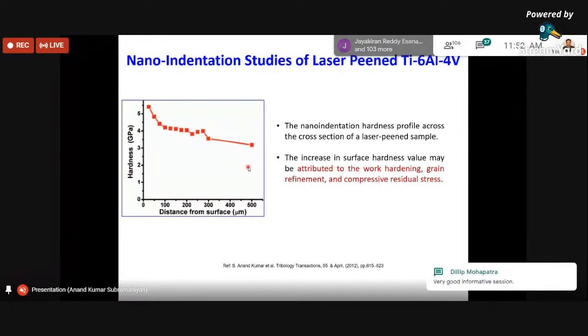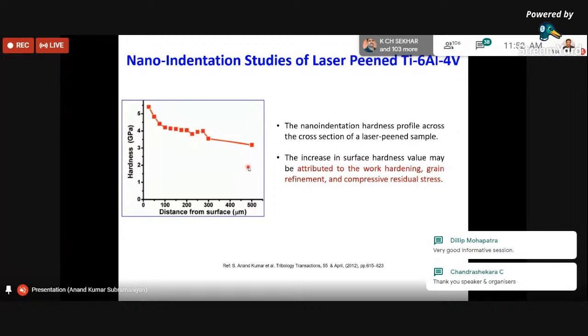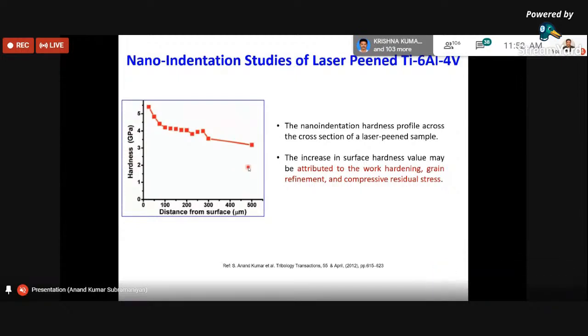But certainly the grain refinement to ultra fine grain formation, for example, people have seen 1 micron grain size and 0.5 micron grain size after doing FSP. And I think it should be possible to obtain nanocrystallites also, but I've not come across it.